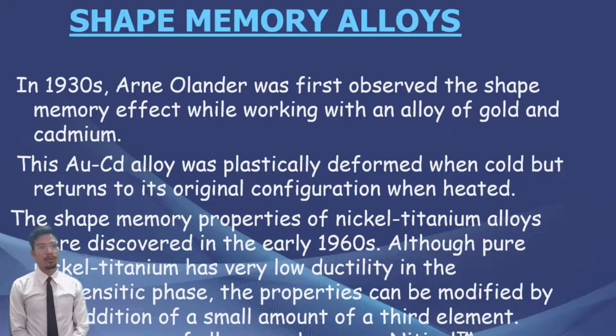And the next slide is shape memory alloys. In metallurgy, a shape memory alloy is an alloy that can be deformed when cold but returns to its pre-deformed shape when heated. It may also be called memory metal, memory alloy, smart alloy, or muscle wire. Parts made of shape memory alloys can be lightweight, solid-state alternatives to conventional actuators such as hydraulic, pneumatic and motor-based systems. They can also be used to make hermetic joints in metal tubing.